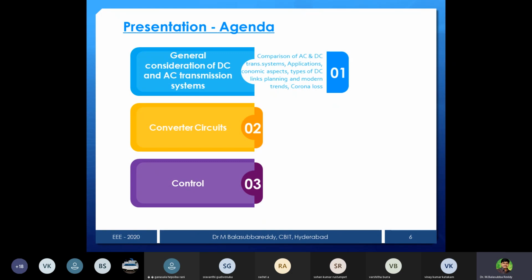But when you come to the DC, what will happen? There is a forced commutation. Why is it forced commutation? Because the input is DC, it won't go to natural zero. That is the aspect there. One drawback I can say is that commutation is a problem in the case of a chopper. We need to turn off the device forcibly by making use of additional commutating elements like L and C. That is the aspect of the rectifier and an inverter.